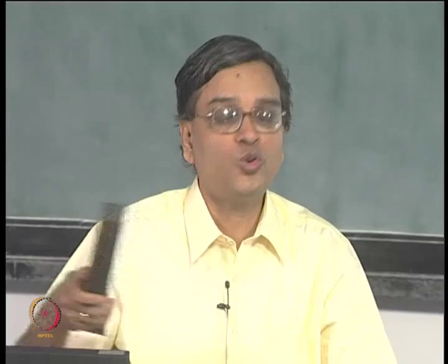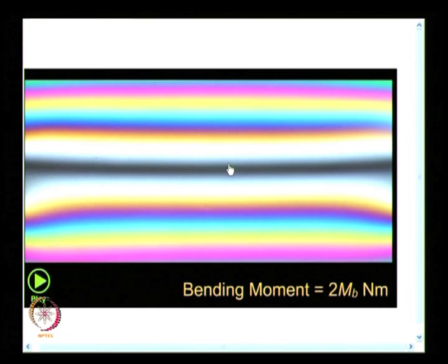So, that is why I said that experiment is giving you truth, and we also noticed the fringe pattern observed in the beam, there was slight variation on the tension side and compression side if you look at it in a subtle fashion. For a quick look it will appear as if it is symmetric, but for a very closer look it will have small deviation which could be neglected as a second order effect and carry on with it. So, the point emphasized here is the moment you come to experiment, do not discard the raw data.